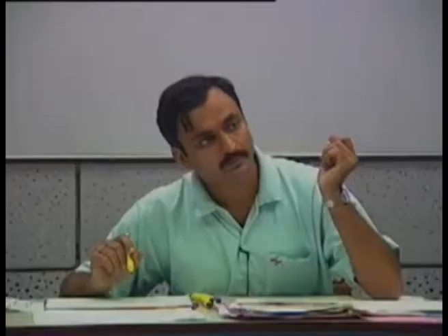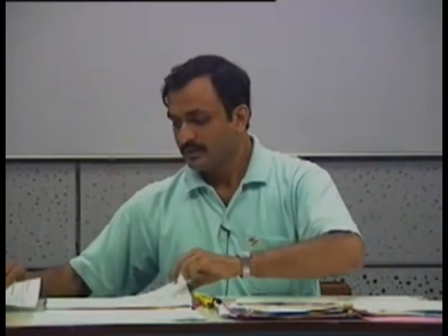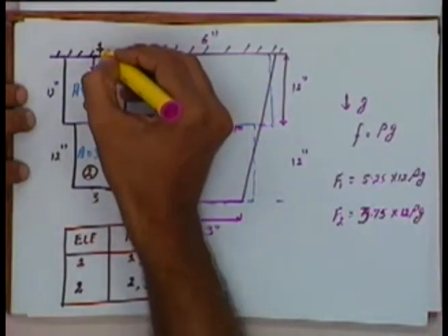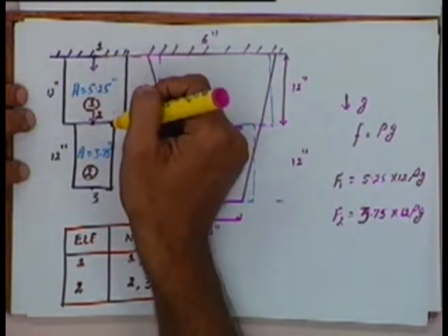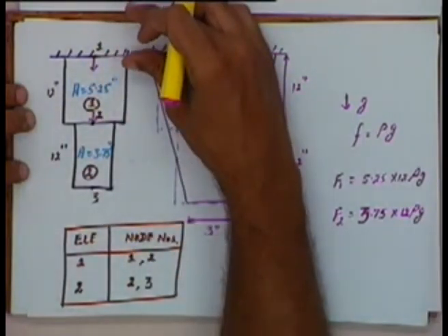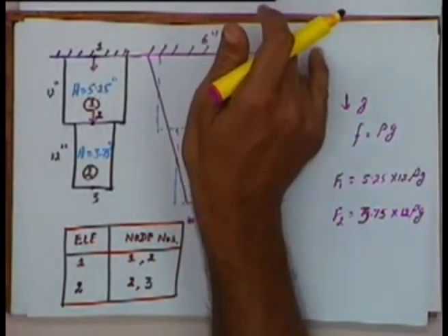Okay, you are saying something? Yeah. What about the force that is acting due to the weight of the lower element on the upper element? See, right now, what we have not done, we have said that the deformation here is, let's say, Q2, and the deformation here is Q1. We haven't yet found out the expressions for Q1 and Q2. When we do that, even that weight will be taken into account. When we solve the global equations, your question will get answered.